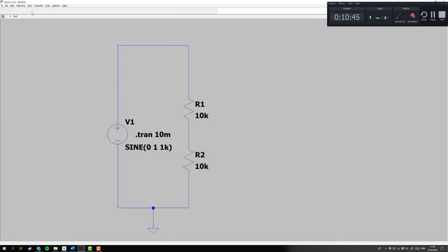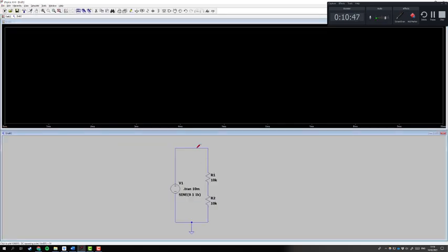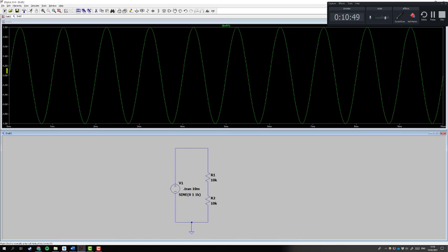Let's run our simulation again. And this time, let's look at the top and see what's happened. So we're going from 0 to 1 to -1. When it says amplitude, it means plus or minus 1 rather than 1 necessarily. These different simulators have different definitions of amplitude.